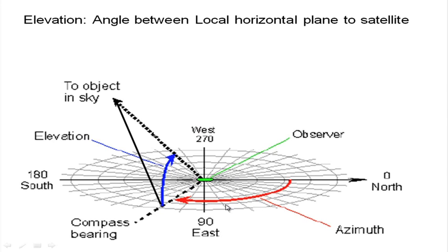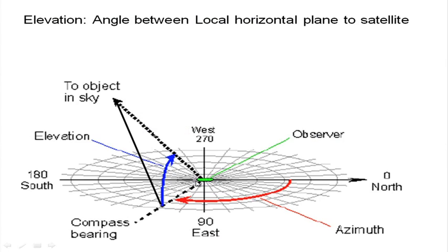So, you orient your antenna eastward and you will again come to that line and you will get the azimuth. So, this is azimuth and elevation. In the textbook different diagrams are there, you can look at those and try to understand, but the main thing is understanding what is elevation and what is azimuth. So, the antenna has to be pointed skyward at the angle of elevation and from the north eastward on the horizontal plane at the angle of azimuth.